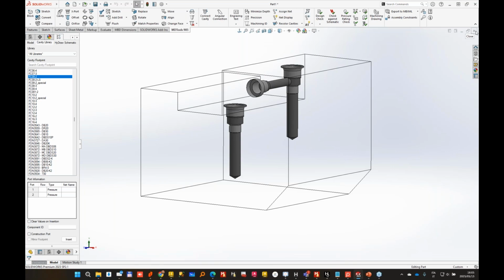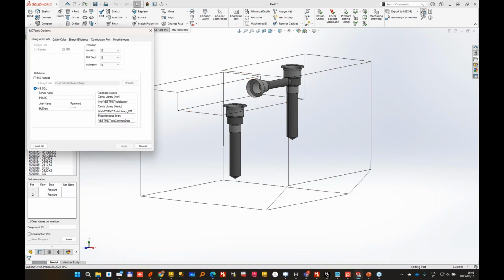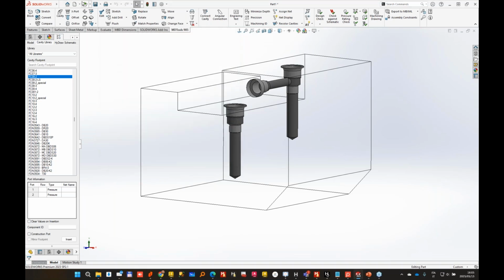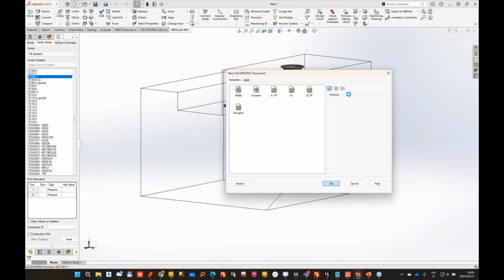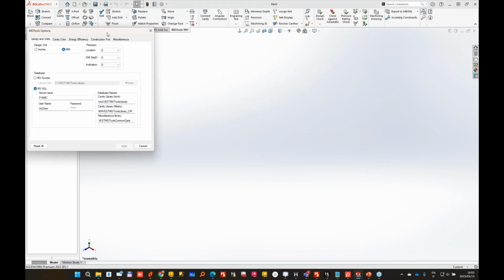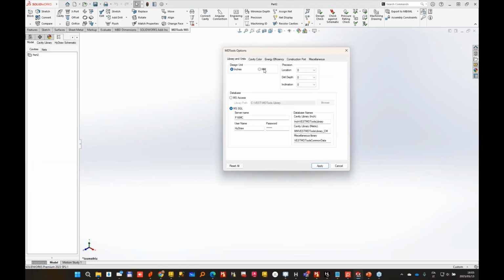While thinking about this exercise, I can see a question: how to change metric units to inch while starting with a block. It's not possible to change the unit on an already designed block. When you start placing it, it will be grayed out. If you start a new part, it will be possible to change the design unit. So I stay with millimeter in any case.